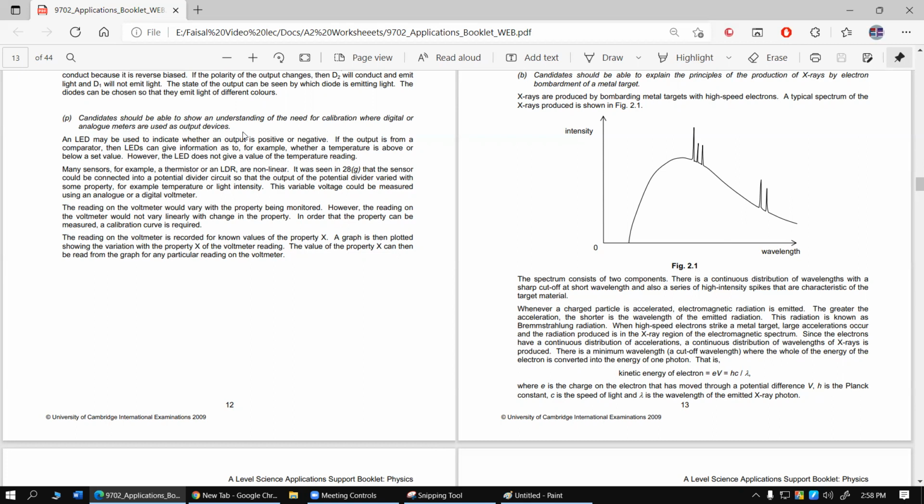I mean all those temperature measurement marks, if you only have the glass thermometer and there is mercury within the glass thermometer and there is no mark around, this is a good thermometer, but this is missing the calibration. Using the thermometer, you cannot take a temperature reading. To be able to take the temperature reading, this should be marked with the temperature scale, and that's what makes it usable. So the process of preparing a component so that quantifiable data can be obtained out of that device is what we call calibration.